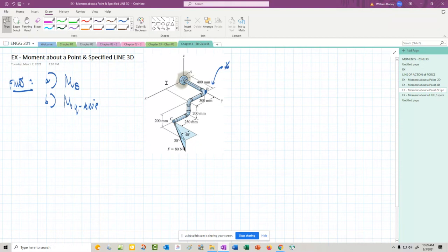Now, I said earlier, maybe we can fake this with 2D. I'm not a big fan of faking a 3-dimensional problem as a 2D problem. I know there are students that will do that. They will hold on to sine and cosine to their last moment, and I get it because it should be easier. But in 3 dimensions, it's okay to use sine and cosine to deal with the force, like on this force, we have to deal with these angles. But to get your final solution by using sine and cosine, I think you're setting yourself up for trouble. So force yourself to understand this R cross F, this 3-dimensional dealing with a force and a distance to get a moment.